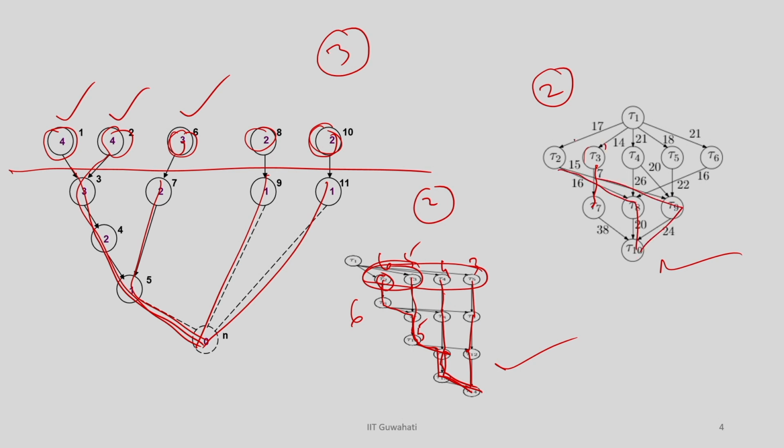So among these 2 I am going to give preference to this node, because if you select this, there are 2 other nodes whose dependency is now resolved. So those nodes will be ready to be scheduled in the next subsequent step. This kind of logic might come as a secondary decision making, but again that may not always hold at any time.